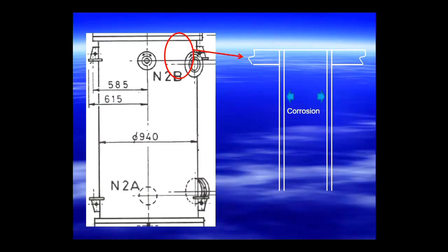The problem is, the very fact that chrome is so reactive means that if you abrade that layer, you instantly get more reaction. So as soon as you start abrading the oxide layer on a stainless steel, it will corrode at a furious rate so long as you keep taking away that oxide layer, which is precisely what was happening with this boiling. In other words, the oxide layer wasn't quite robust enough to resist what was going on at that level. Any impurities in the acid would accumulate at that surface and abrade that chrome oxide layer. So the thing just got eaten out.